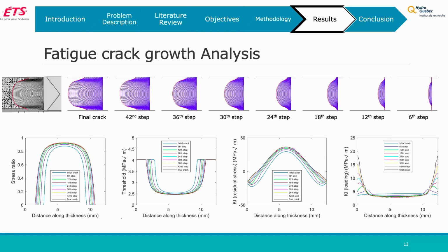So in the middle, the SIF stays kind of constant and similar, but as the crack forms that tunneling shape, the driving force on the sides increases despite the decreasing load. As you can see, for example in the last one, the SIF on the sides is very large.